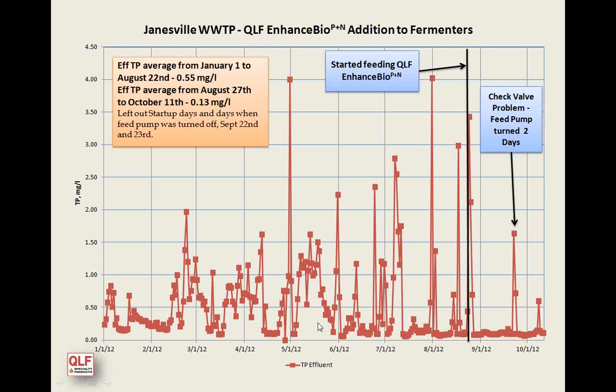And you can see this is from the first of the year until when we started. Here it's not too bad, but you can see this time frame here, which is about a 2-month period. We had a couple spikes. This was a spike because we had a check valve that plugged in our trial setup, and so the pump was shut off for 2 days.